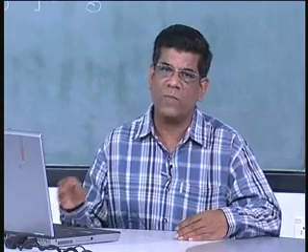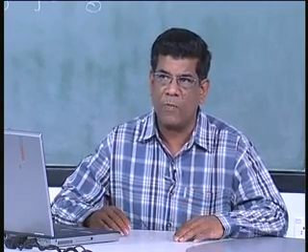Because you also know the lower the gain. How do you lower the gain? The only way you can lower the gain is by giving feedback, and that is negative feedback. And once you give negative feedback, we have already seen when we discussed negative feedback that you have a lot of good things happening to the amplifier. The input resistance increases, the output resistance decreases, the bandwidth increases, distortion decreases, etc., and they are all by the value of gain that you have sacrificed.